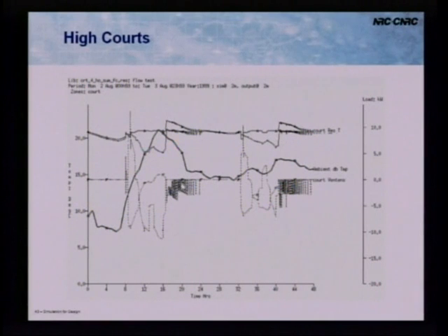The other thing here is we're simulating at very short time steps, a 2-minute time step, and you can see all this oscillation here as the natural ventilation dampers were controlled with an on-off control. So they were busy opening, closing, opening, and closing, opening, and closing. So there was a control issue here. And as we were developing this model, questions were going back to the engineers: how exactly are you going to control this? And they were saying, we just want to know the size of these openings. We don't want to think about the control just now. So there's got to be that interaction between where you're creating the simulation models and the details that you need there, and also what's appropriate at the design stage.